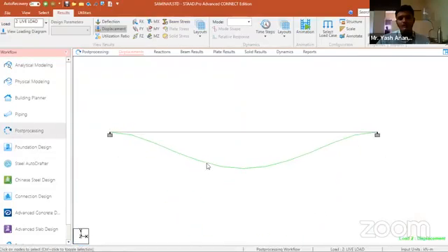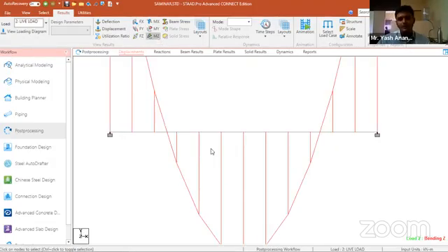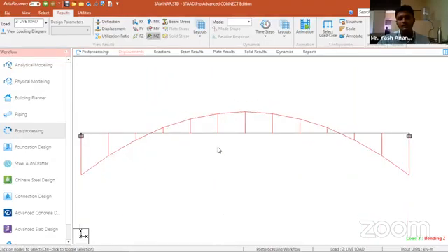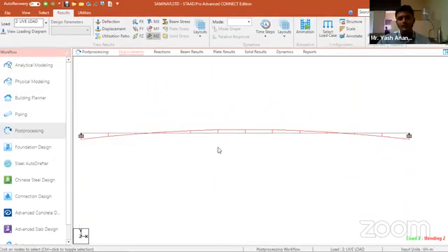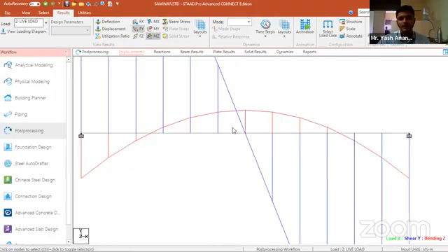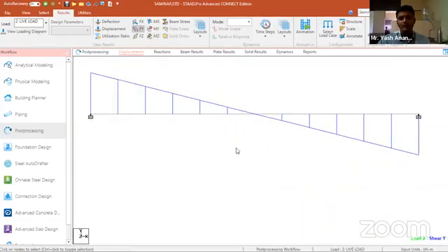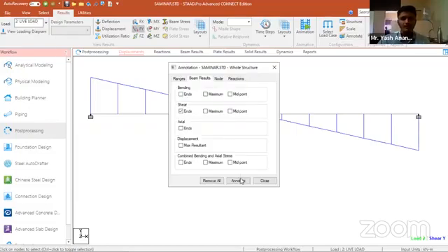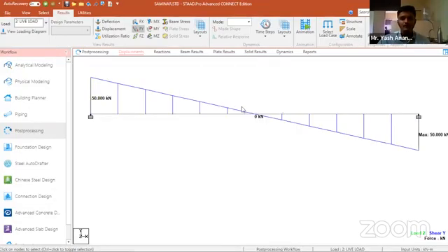Display at this time. For that, the deflection curve is like this. Okay, we have to see the bending moment. There is the bending moment curve, you can see. Okay, fine. If you want to see shear force and bending moment, and if you want to see the value, go to the shear force. Okay, as you can see, 50 kilonewton, 50 kilonewton. At the center there is 0.